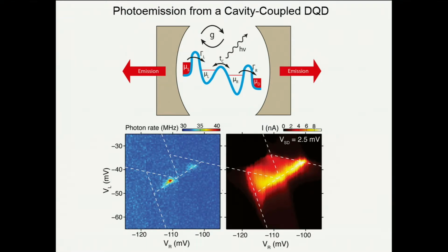And what we did in this experiment was just hook the cavity output up to a spectrum analyzer. And we measured the power spectral density of the radiation emitted from this cavity, and you can actually see a small photon emission rate. But these experiments by Yin Liu showed that we'd actually get light out of this device through a single electron tunneling process. And so when an electron tunnels from the left dot to the right dot, every 1,000 or so tunneling events, you get 1 photon out. And that signal was just above the background noise of our amplifier.